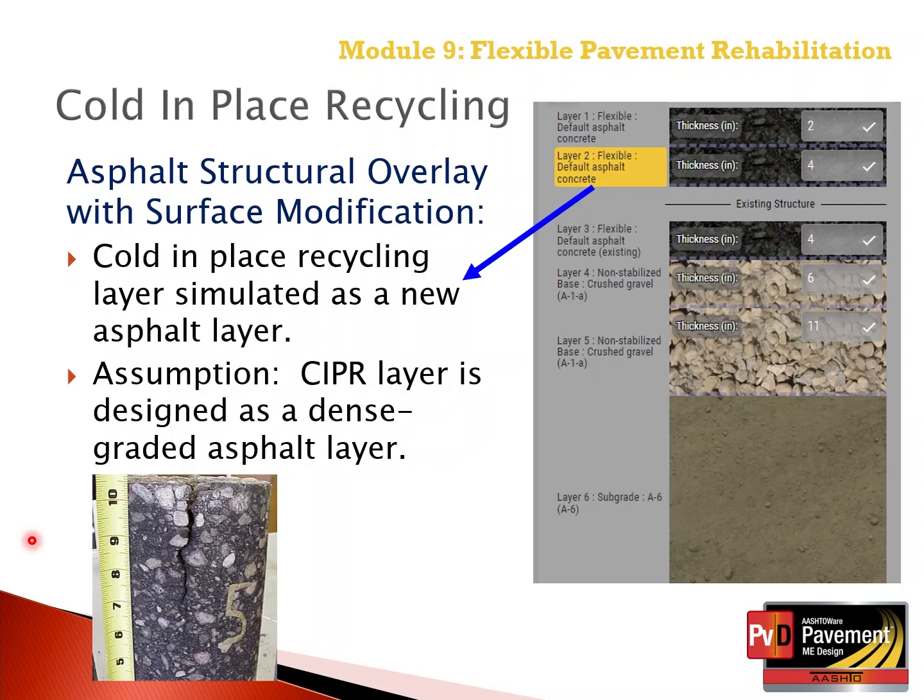and/or start propagating below the wearing surface. And in addition, there could be some material surface defect, like longitudinal aggregate segregation or truck-to-truck segregation from the construction placement process, or raveling at the surface, or other types of surface-related distress.